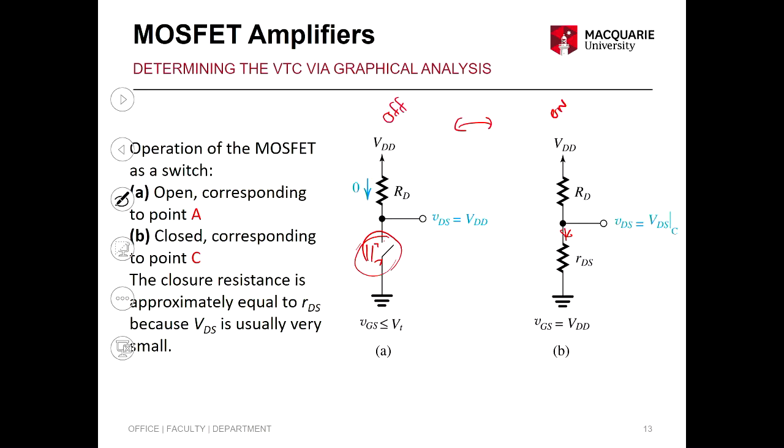Now this is mainly the digital domain, and we don't really do a lot of stuff in the digital domain. What I mean is that this course is more analog electronics, amplification. But on and off is a NOT gate. You can just create a NOT gate, and once you create a NOT gate, you can create any gate from that, right? So that's a basic building block. As long as you know how to build a NOT gate from a transistor, you can use it as a base building block and then create your digital circuits.